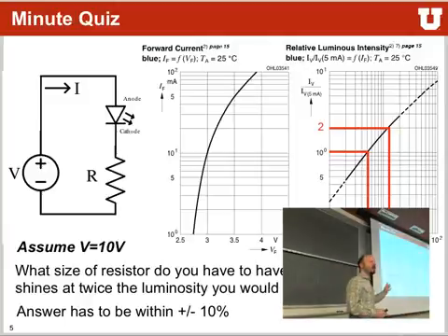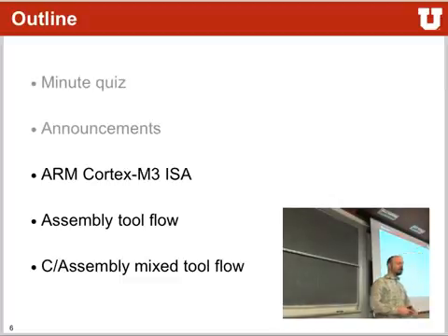And you will also find out that with LEDs, it really doesn't matter that much what your resistor is. Plus minus 10, plus minus 20% is absolutely fine. The LED will still light up most of the time, just sometimes a little less bright than others. Now the tricky part becomes when you have LEDs of different colors. If you want them to shine at about the same brightness, you really have to adapt the resistors to different values. Or else you will have a blue LED that is extremely bright and another LED that's just not bright at all. Okay, so let's keep going.